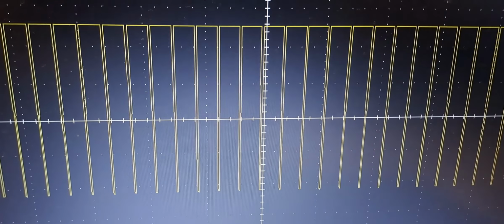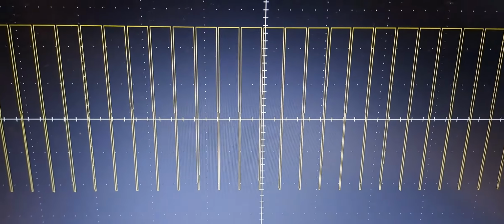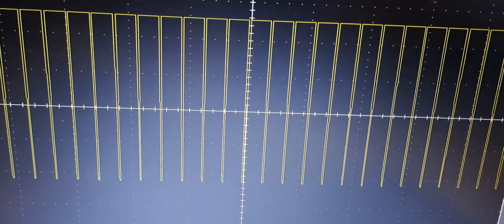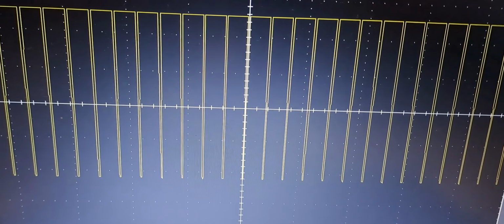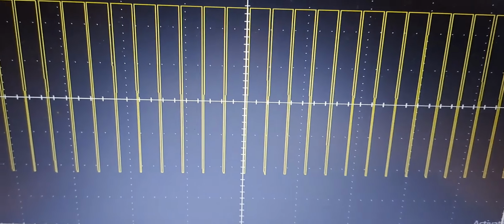So this is how the circuit works. I am getting two frequencies. 10 kilohertz means logic 0 and 48 kilohertz means logic 1. We can design the demodulator accordingly. In the next video, I am going to design a proper demodulator for this circuit so that we can detect the two logic states.